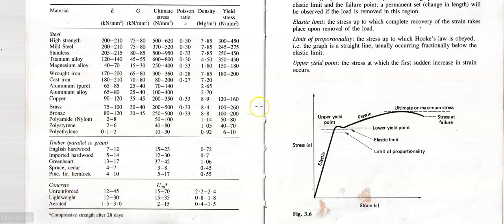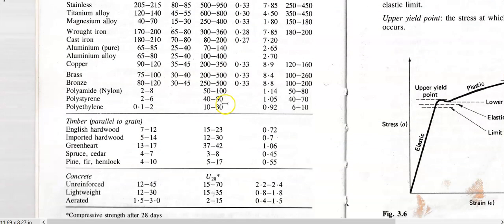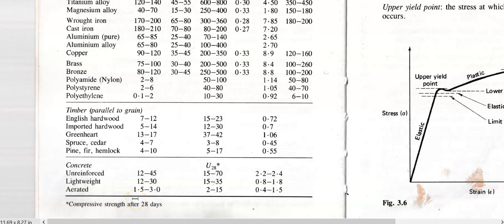Does anybody know what the word aerated means? Aerated means that when you make concrete, as we pour it, or stir it, or place it, we introduce bubbles of air into it. We say it's aerated. I'm sure you like chocolate. If you eat Aero, doubly bubbly chocolate, yummy. There are little bubbles in there. That's aerated chocolate. When you introduce bubbles of air into a liquidy material, it becomes aerated. So we aerate concrete to still keep its strength properties within a certain limit, but we make it a lot lighter because there are lots of gaps in there.